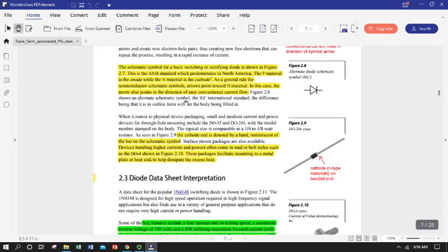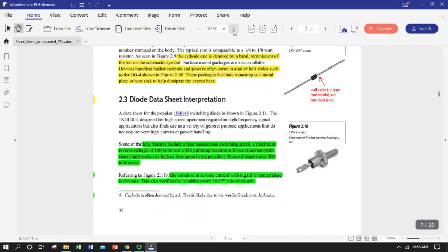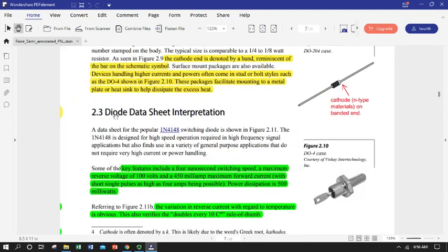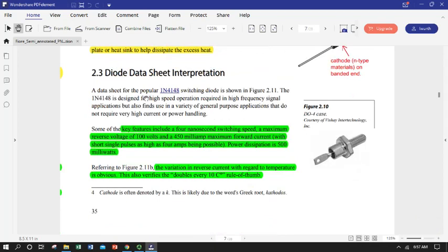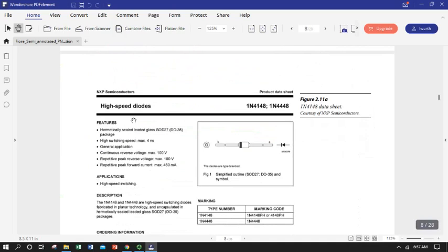So lucky for us, a lot of the things that we want to know with respect to those points are available in our diode datasheet. So for every device that you can purchase, you'll get a datasheet that basically says what not to do and what to expect if you operate the device under appropriate conditions. And so these are the manufacturer's data sheets. So we're going to look at a real live diode, a real live PN junction. It's 1N4148. There are lots of different manufacturers that make it, and the data sheet is represented.